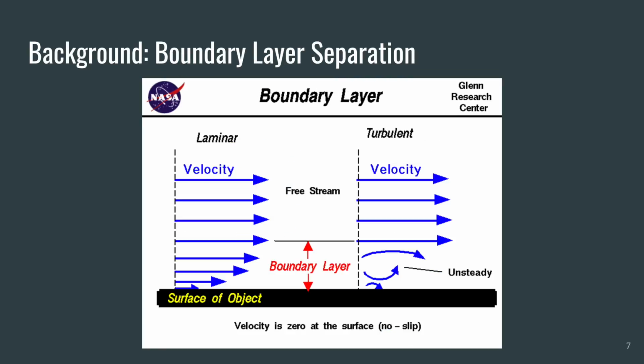the boundary layer. Boundary layer separation occurs when the boundary layer lifts off or separates from the body and creates an effective shape much different from the physical shape. This happens because the flow in the boundary layer has very low energy relative to the free stream and is more easily driven by changes in pressure.